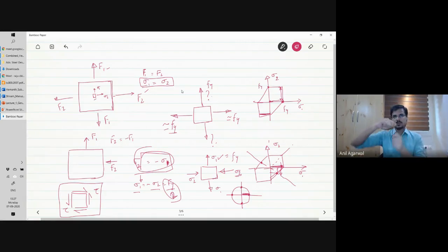If I do a uniaxial tension test, it yields at Fy in tension. Let's say 250 MPa. At what value of tau will it yield? I think I have just given all the answers here. First you need to look at the Mohr circle for this tau, then you look at the corresponding sigma 1, sigma 2.